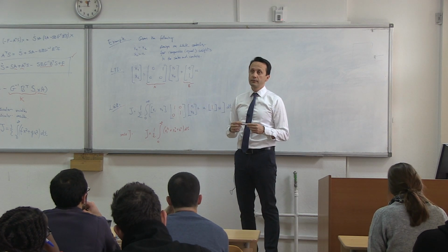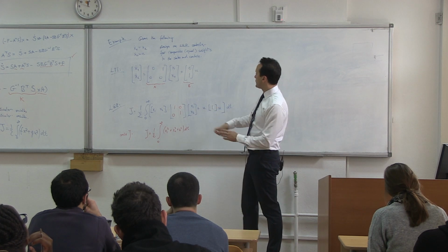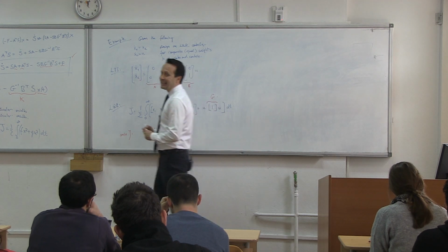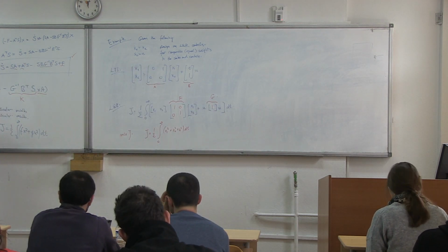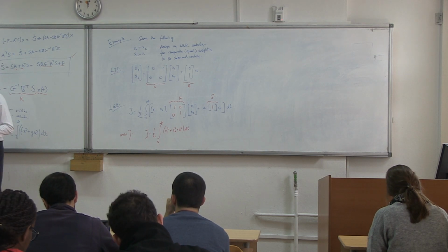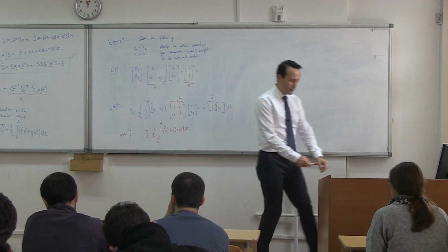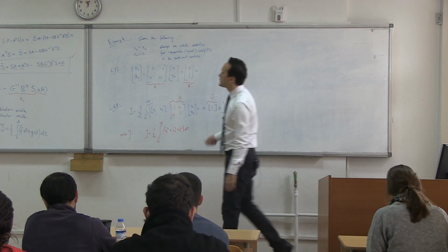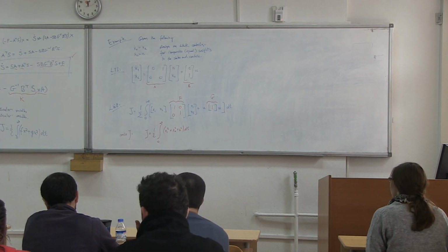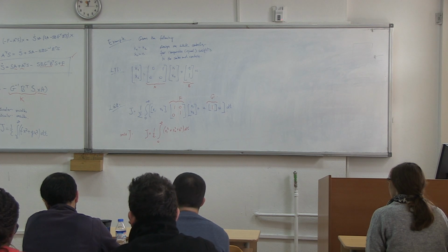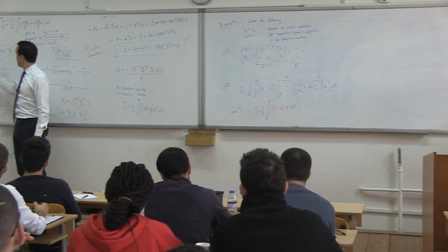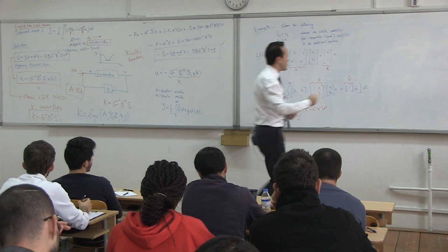Does that make sense? Okay, so let's say I choose this. Now this is F, and this is G. If I had MATLAB, all I need to do is write these numbers over here, write LQR, and say K is equal to this, and boom, you have the result. But let me just show you what it looks like if you don't use your computer. You know G, you just take the inverse. You know B, right? You don't know S, so all you need to do is find S. In order to find S, you need to solve this equation, the algebraic Riccati equation.